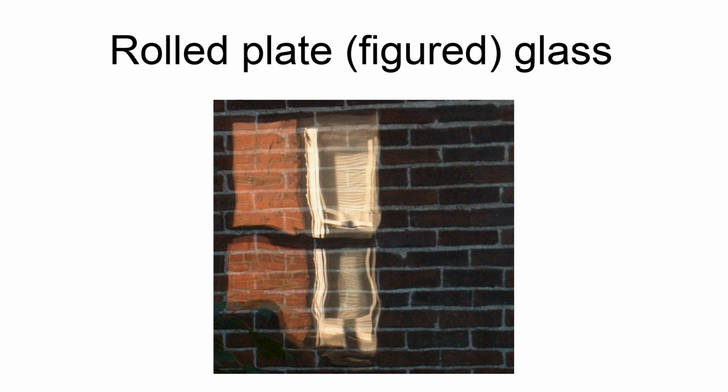The pattern is impressed upon the sheet by a printing roller, which is brought down upon the glass as it leaves the main rolls while still soft. This glass shows a pattern in high relief. The glass is then annealed in a layer. The glass used for this purpose is typically whiter in color than the clear glasses used for other applications.